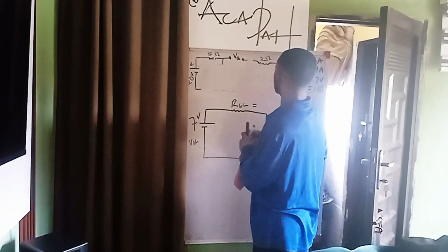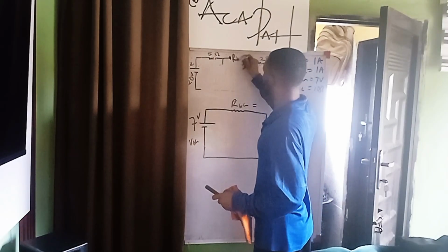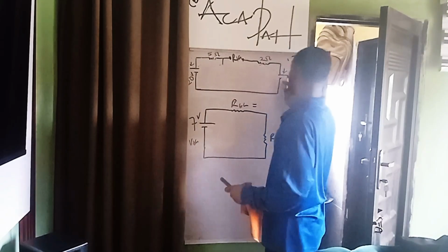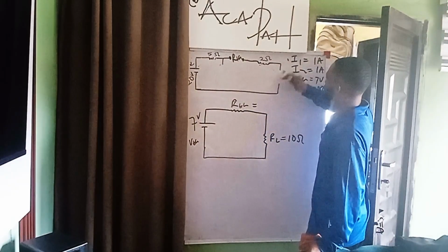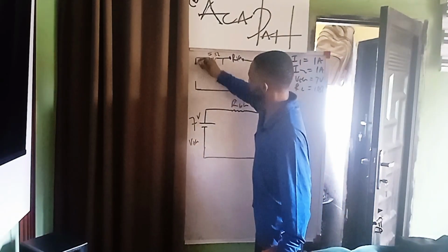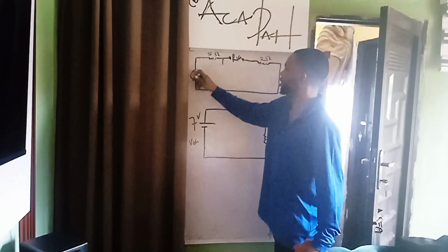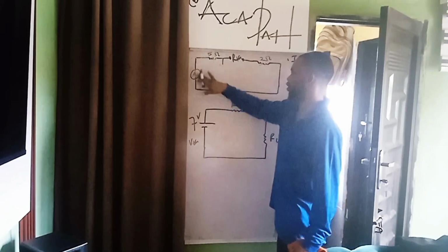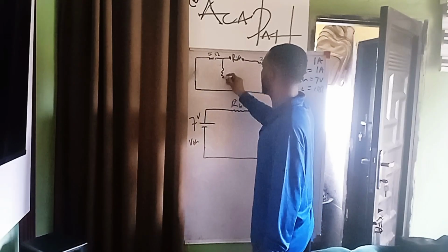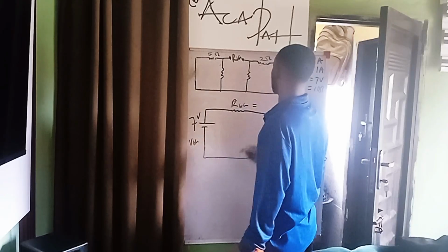So all we need to do is to simply say, now it's going to be RTH we are finding from this point. To find RTH, Thevenin resistance, short circuit this. So turn everything that is an external voltage, that is giving voltage, and everything that is a given current as well, short circuit it. So make it a wire. When I say short circuit, it means make it a wire while the resistance remains. If I say open circuit, it means cut the wire.